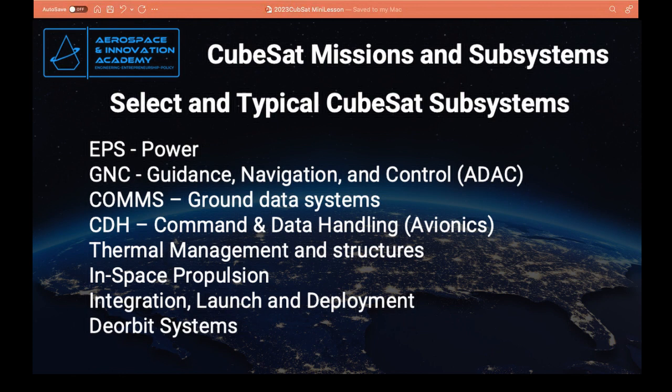So there are two major types of antennas that I'm familiar with and have a little experience with on the CubeSats. One is called a ceramic patch antenna. It is literally about 1.5 centimeters, less than an inch on a side square. It's probably about a quarter inch or 5 millimeters thick, and it sits right on the face of the CubeSat. That's one type of antenna.